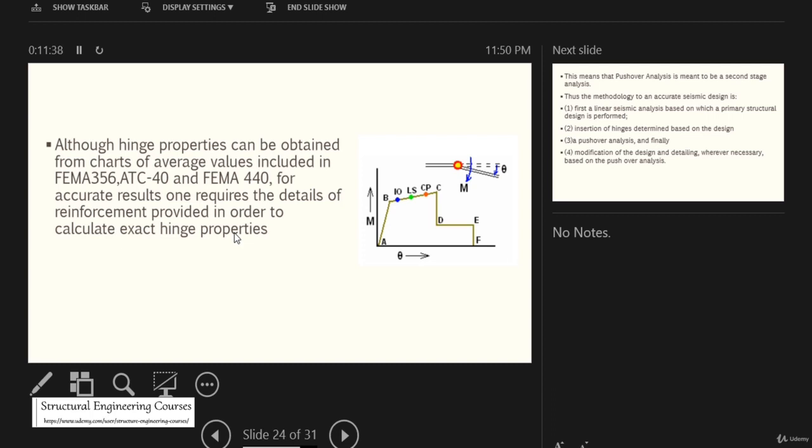So it is like we do not say that only concrete will stand against the earthquake. We think that for the rotation and all the hinges that shall be formed, reinforcement shall be equally responsible also. So all the good software do ask us what exactly is the reinforcement in the beams and columns while doing the pushover analysis, and what exactly is the reinforcement in the ductile zones also. So that is also asked in the ETABS and SAP software or in Proto Structures, let us say.